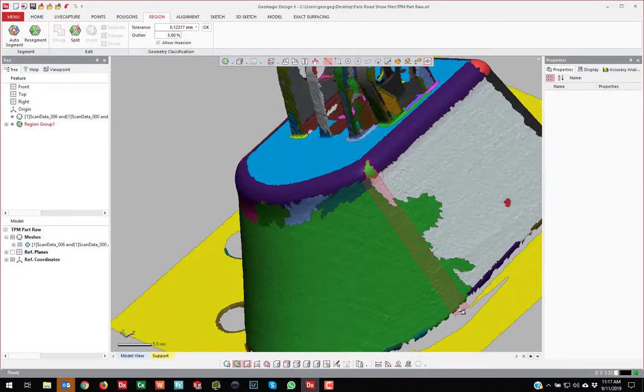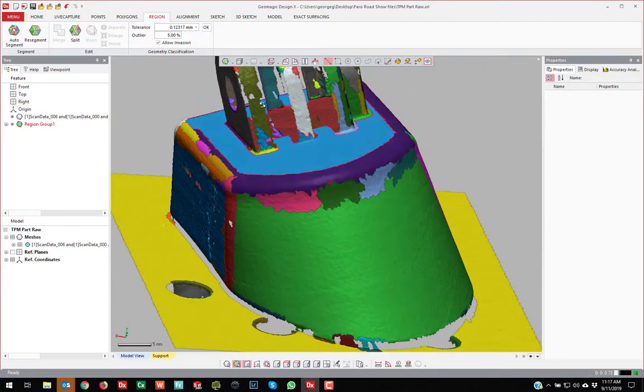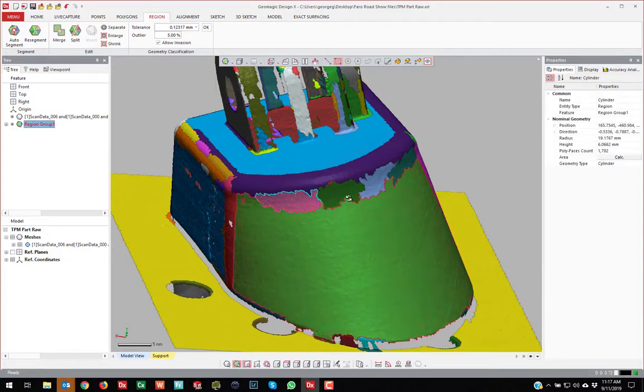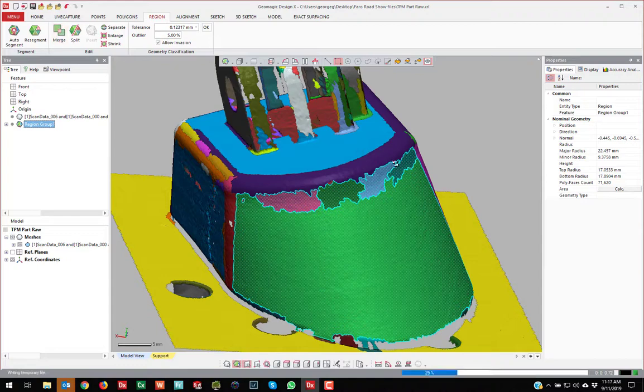So if I want to grab this area here and then say insert, and with these small areas here, if I want to merge those all together into one big green area, I can. So I can come in with the rectangle selection tool and hold shift and grab all these regions and say merge together.